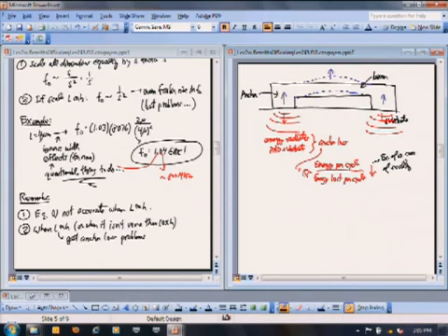And so there's a couple ways to solve this. And let me make that remark number 3. So coming from that, remark number 3 is the solution to this, or one of the solutions, and that is to use nano dimensions. Okay? Don't just scale L, scale H too. Okay? But if you scale H, right, to get to 1 gigahertz frequency, you got to scale L more than